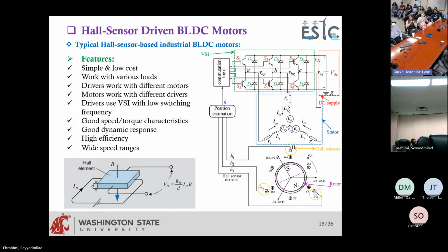So if you have higher harmonics here, you can expect to have higher harmonics in the current. Let's say that these are pure sinusoidal. If you have higher harmonics here, you can expect that those harmonics should flow. If you do superposition, you do it once for the fundamental component and once for the harmonics. For the harmonics, these are going to be equal to zero, superposition, right? It's going to be those harmonic voltages divided by this impedance. So if you have higher harmonics in the voltage, you'll have higher harmonics in the current.